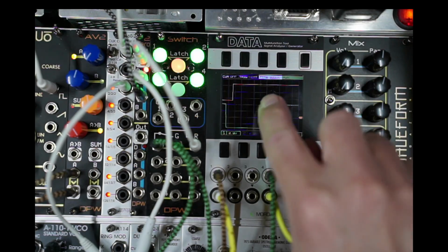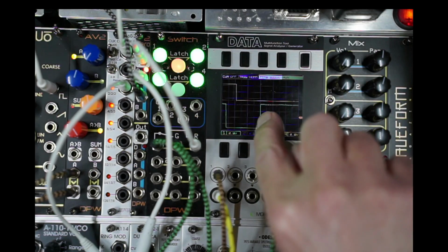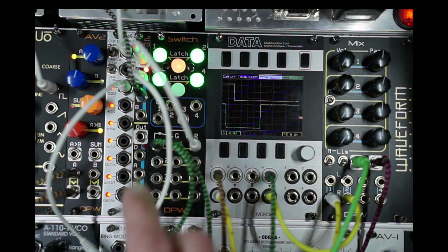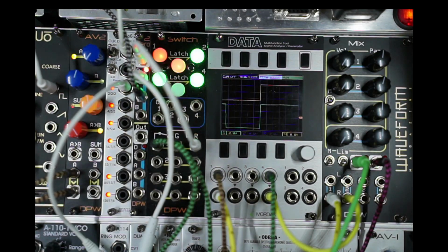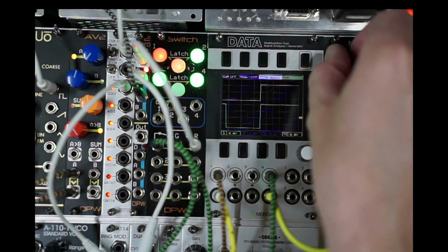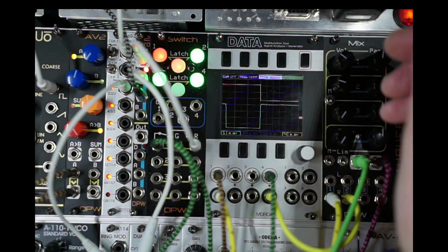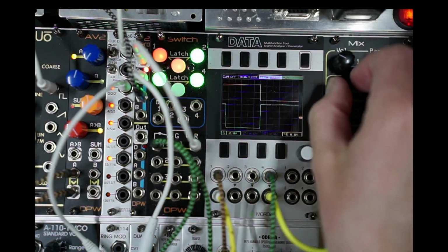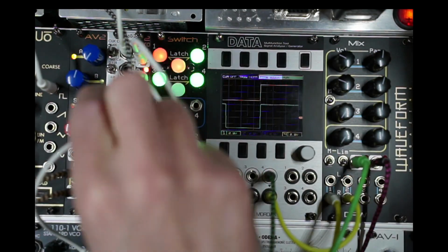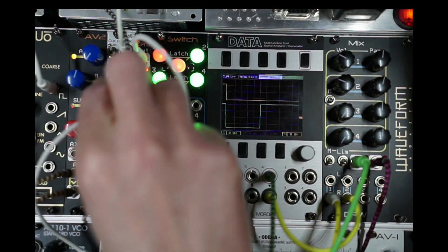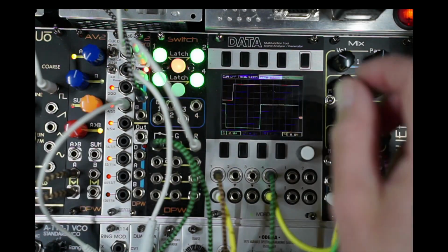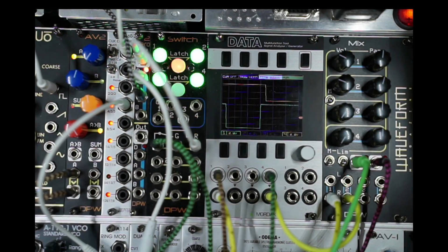So what I'm doing is I'm using this flank to reclock what's coming out from the Zero module, and that way I have stabilized things, and then you have your clean signal and your subdivision. So you can go by divide by 3 or 5 or something. If I turn it off again, you get this strange behavior again.